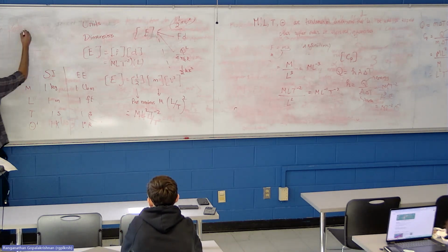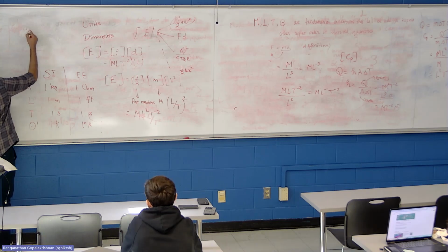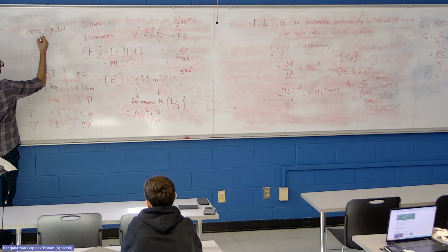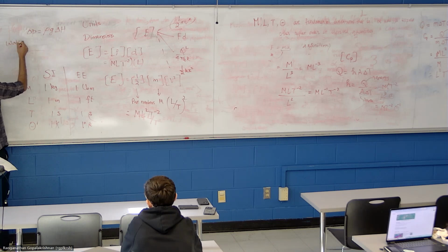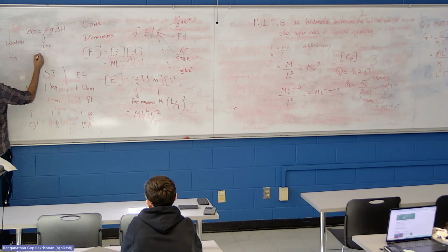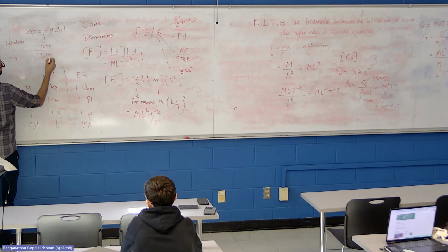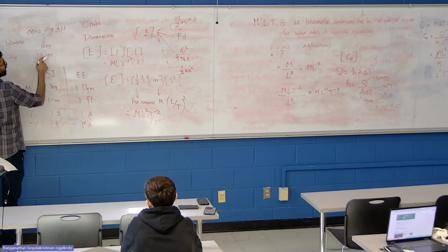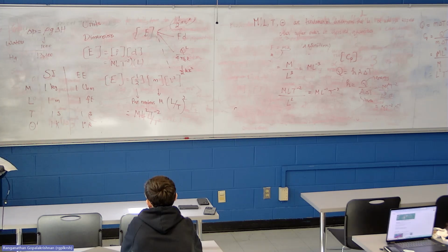It's like saying delta P is rho g delta h. For water, rho is 1000, and for mercury, it is 13,600. If you swap mercury with water, you have to get a deflection that is 13.6 times bigger. So your column, if it is 1 meter, has to be 13.6 meters. Okay.